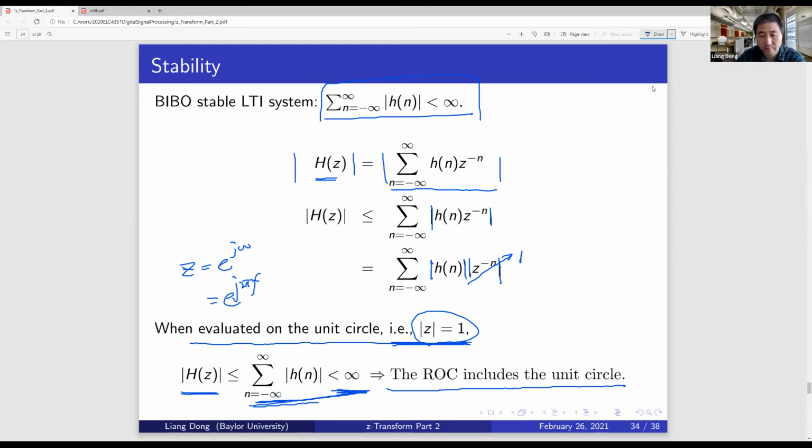That's a special case of the Z transform where z is in polar form, amplitude times e to the power j omega. When rho is 1, or the absolute value of z is 1, we only look at the unit circle, and we only care about the frequency. It has a special meaning because later on, for a real system, we are checking everything with the frequency.